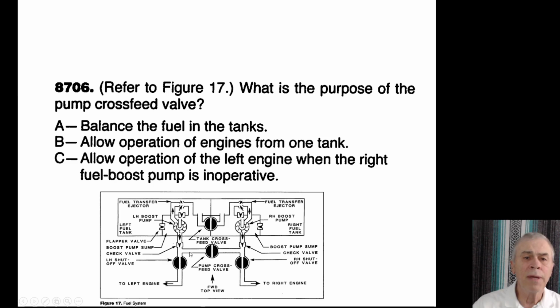And here's where they're going to make a differentiation between the two valves. You can see above is the tank cross-feed valve, and below is a pump cross-feed valve. They're going to refer to this figure and ask what is the purpose of the cross-feed valve. You don't necessarily need the figure for that type of question. What is the purpose? A, is it to balance the fuel in the fuel tanks? Or B, to allow operations of engines from one tank? Or C, to allow the operation of the left engine when the right fuel boost pump is inoperative?